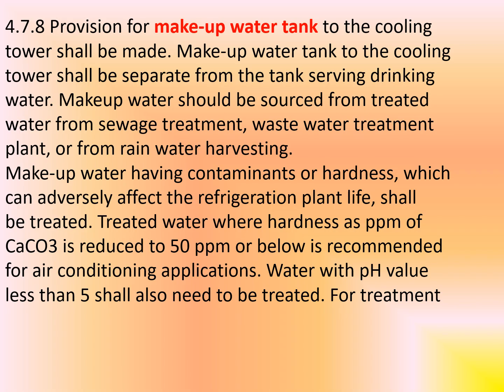First, makeup water should be sourced from treated water from the sewage treatment or wastewater treatment plant, or from rainwater harvesting. Makeup water having contaminants or hardness which can adversely affect the refrigeration plant life has to be treated.